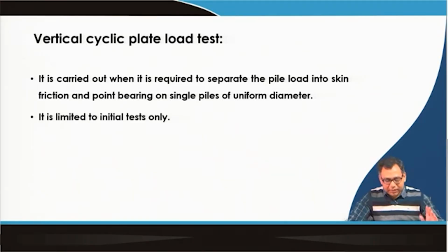So, as I discussed, we can conduct the plate load test, and that was the static plate load test, where we increase the load in steps continuously. But there is another plate load test that I have discussed, that is the vertical cyclic plate load test, where there will be loading, unloading and reloading. The purpose of conducting the vertical cyclic plate load test is that we can determine